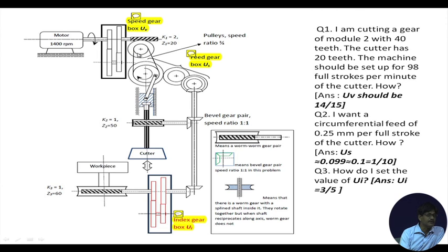Coaxial with the worm gear, we have not a pinion, but a pulley attached. This one is a pulley and it has the same rotations per minute as the worm gear. With this pulley we have a belt, and this belt goes all around a larger pulley at this position. So we will effectively have rotation of this larger pulley due to the belt connection with the smaller pulley.